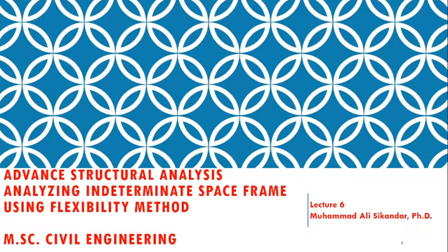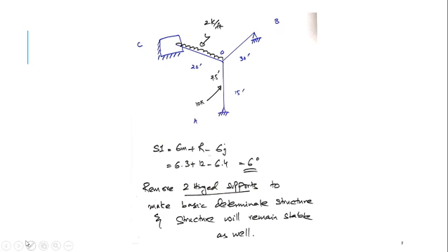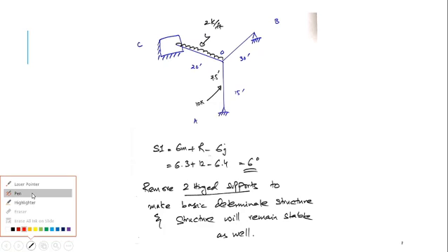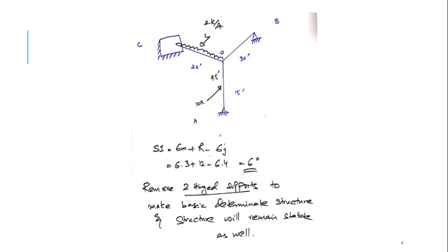Okay, this is a space frame and it has got 3 supports. We have to find first its SI. So SI should be measured using this formula, 6m plus r minus 6j. You have got 3 members, 1, 2 and 3, and we have got 12 support reactions because this vertical, this in x direction, this in z.